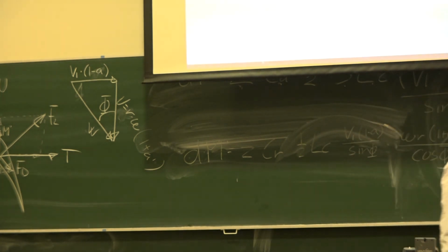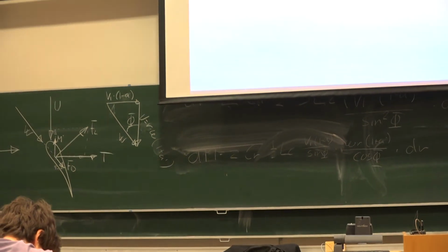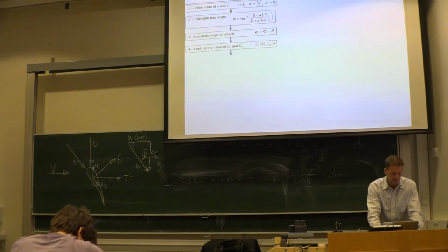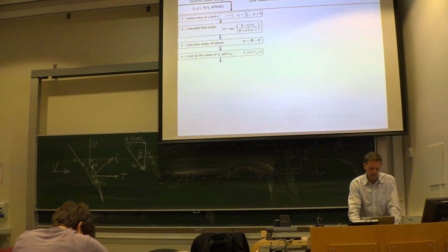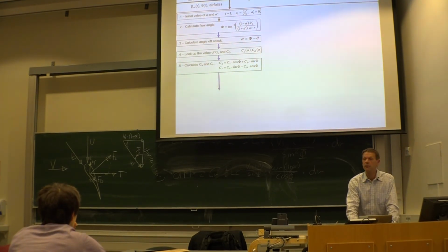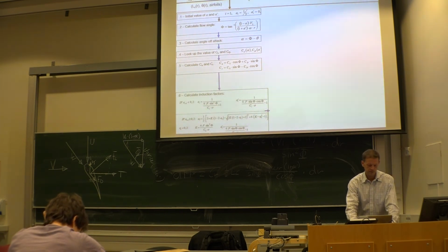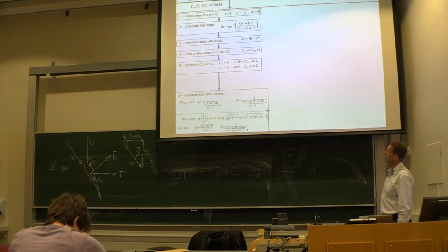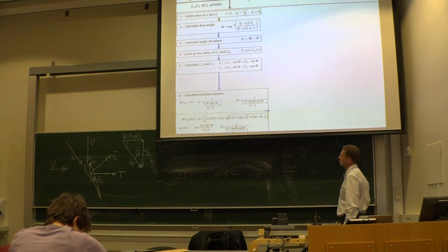Based on that, you're able to find the angle of attack for each element. When you have the angle of attack, you can look up and find lift and drag coefficients. And when you have those, you can calculate C_A and C_R. And now you're able to calculate the induction factors.